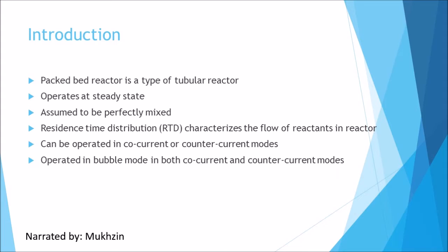It can be operated in co-current or counter-current modes, where the former is most common in the oil and gas industry with the aid of catalysts. The PBR reactor used in our experiment was operated in bubble mode, in both co-current and counter-current modes. These operation modes are most suitable when liquid reactants are treated with a small amount of gas.